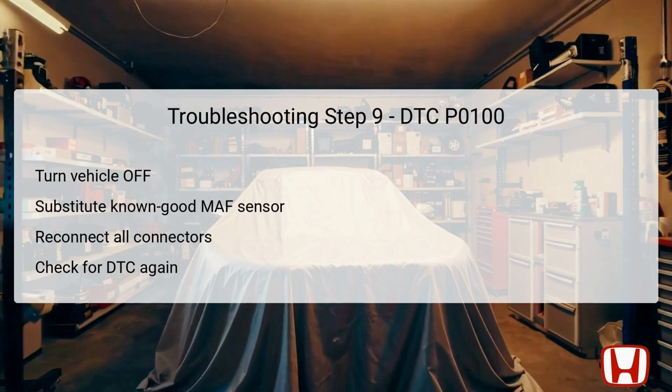Wait for approximately 2 seconds or more, and then scan for pending or confirmed DTCs once more to verify whether the issue has been resolved. If DTC P0100 is no longer indicated, the sensor was likely the source of the problem. If it persists, further investigation into the PCM may be needed.